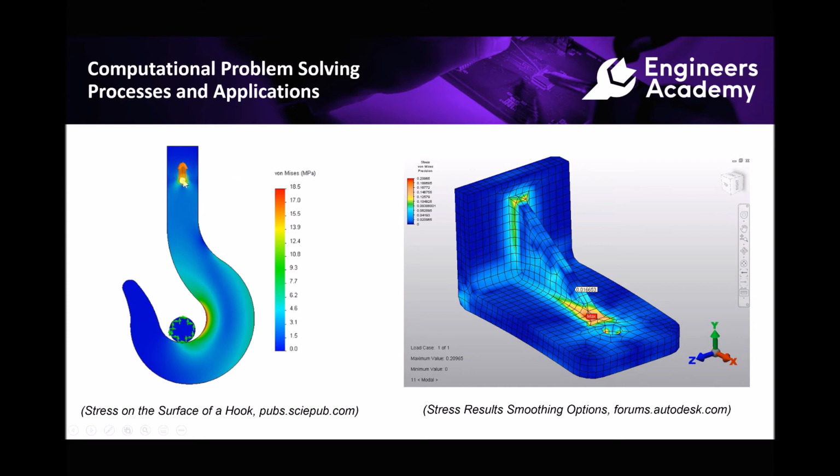We said previously that we'd have a cable or a chain passing through the hook here. What we would need to tell the software is whether the chain and hook were capable of moving independently of each other. So could this hook swing in theory? Or are the two components mated together with a fixed connection? Again, is our load free to move? Are these two surfaces mated together, or is this load free to roll from side to side? There'll be lots of other boundary conditions that we could apply, but this is really just to give you an understanding of the importance of defining boundary conditions as accurately as possible. Now, the same is true for our example on the right-hand side.